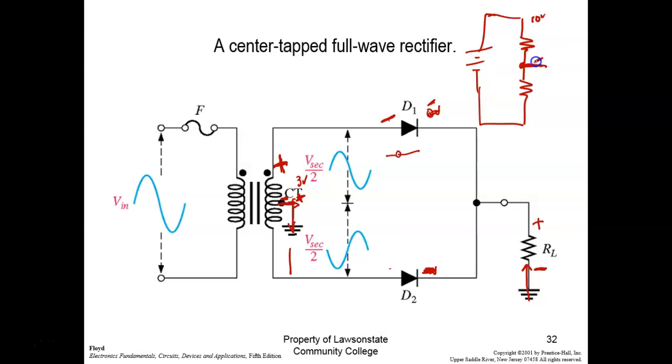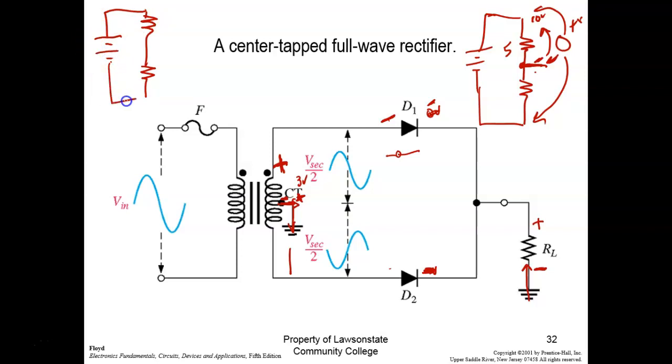Okay. So that means if I was to come over here and take my meter and put it across here, it might be dropping 5 volts. It's going to show a positive 5 volts. Right? You understand? Now, if I was to take that same meter and put it here, I put my black lead there, my red lead there, it'd show plus 5 volts. Well, what if I just left my common right there and put it right down there? What would it measure? You're right, it's going to be 5 volts, but it's going to be negative 5 volts, and this is what we're doing here.